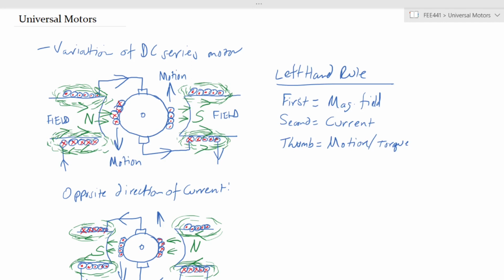Now, in this particular case with universal motors, you have an electrical connection, because you need an electrical connection between the field and the armature. These 2 points of connection, which are indicated here, represent the weak points in the design of the motor. At this point, you have physical brushes, usually made of carbon, which connect the electrical current from the field to the armature. So these carbon brushes tend to wear off with time.